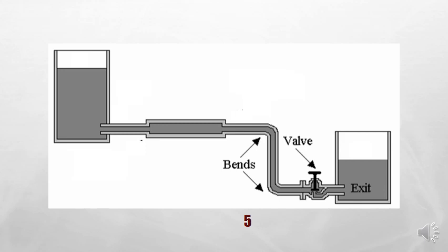Basically we want to move the liquid from this reservoir into the second tank here. As the liquid flows, there could be a loss here because it leaves the tank from a huge space into a smaller space, because the diameter of the pipe reduces the space for the liquid flow.